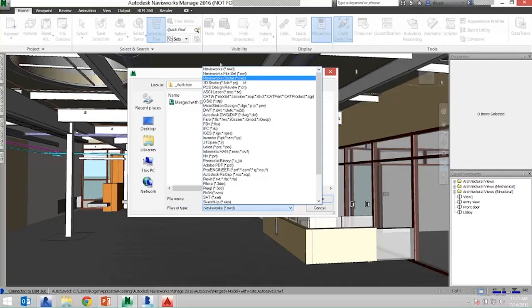So when we say that there's going to be product integration and more ability for Navisworks to read formats, that means that Max will be able to create an NWC. Civil 3D will be able to export NWC files for Navisworks to read. Essentially, an NWC is an optimized version of that file. Now you see there's always been 3D Studio, there's been laser formats, there's CATIA formats.